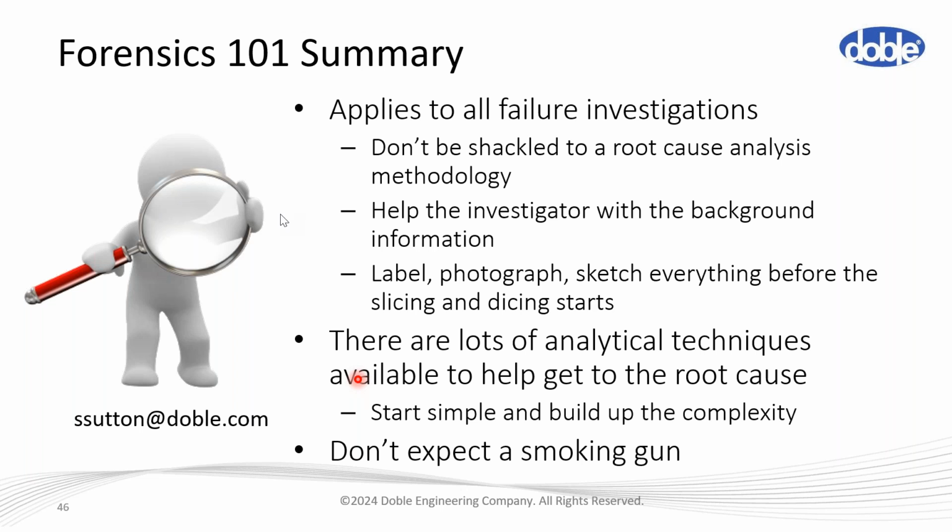That said, there was a utility in the US some years ago that had a very wide geographic area, and they used to deliberately go out and overstress their cables with VLF testing as a way of killing off the weak cables.